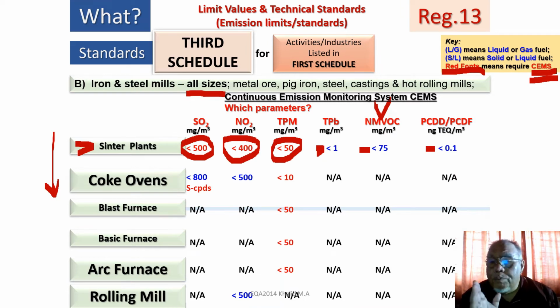So you got to do a baseline study first, because we need to identify for the first time which non-methane volatile organic carbon is emitted from our operation, because this is going to be a long-term monitoring process. You can't afford to monitor every known non-methane volatile organic carbon. It is not cheap, and it is not related to you. What for?